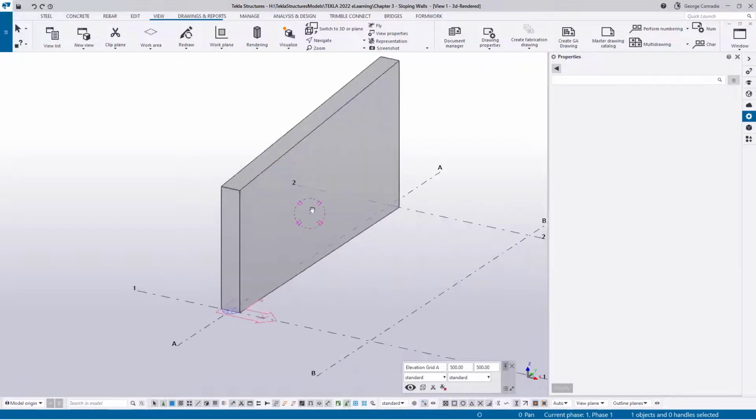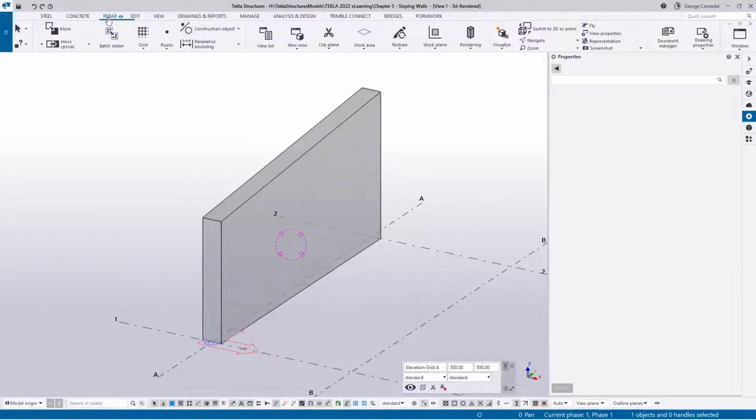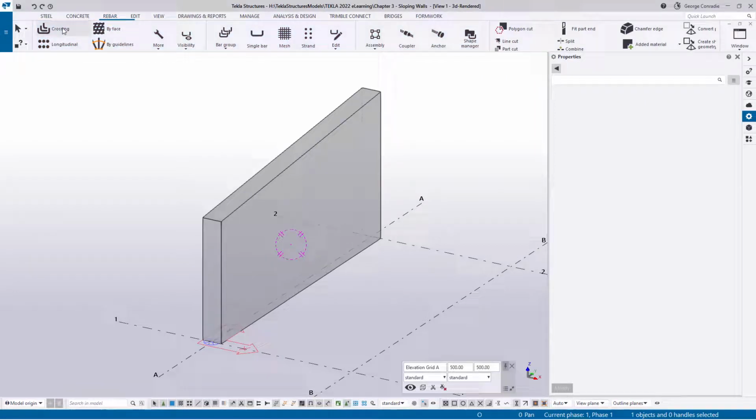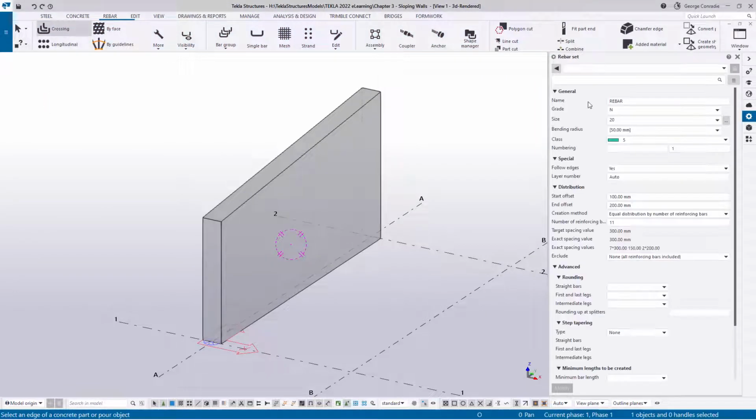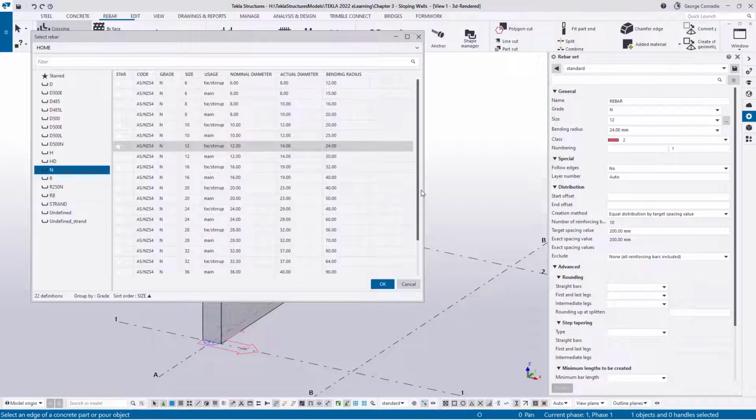the first thing we're going to do is go transparent. And then what I'll do is I will enable the rebar menu and say crossing bar. Make sure that I load my standards in case I've set anything that I didn't want. And then I'll pick a bar. So at this point, what we're going to do is we've got to decide which bars are going to go in first and last. And it doesn't really matter that much because we can always flip the layer priority later.